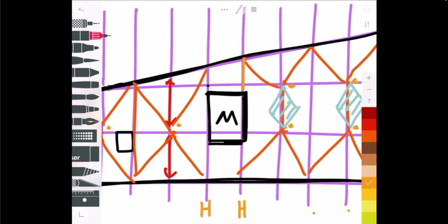But what I would do in this case is, this is a high point along here, and this is a high point along here. So these beams here are installed flat, basically. And so I would probably just approach this area in here as being either sloped insulation to a drain itself, or in this case, it's a pretty small roof area. So I would probably just put a high point of the insulation there and slope it down that way and slope it down that way. And I do the same thing here. But certainly you could do a drain in the middle and do something like that, I suppose. It would work as well. But yeah, I'll just stick with what I wanted to do there.